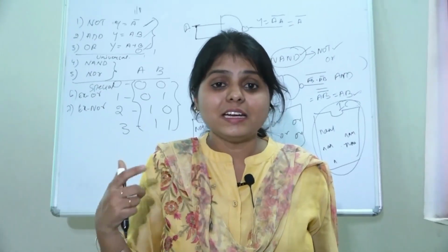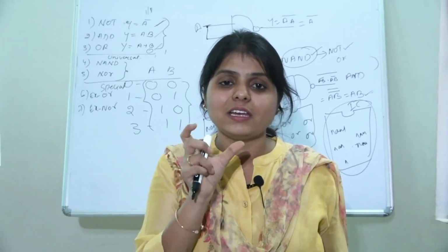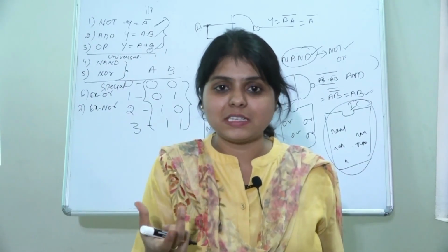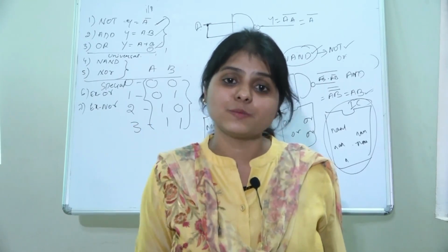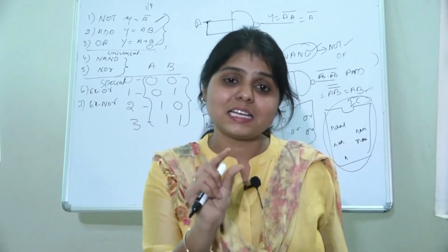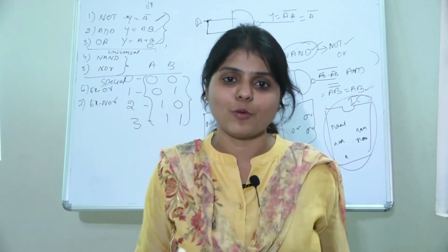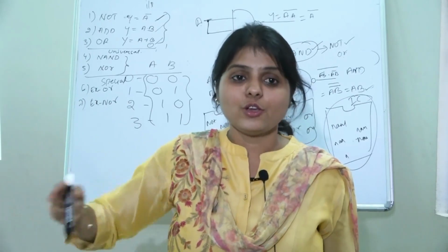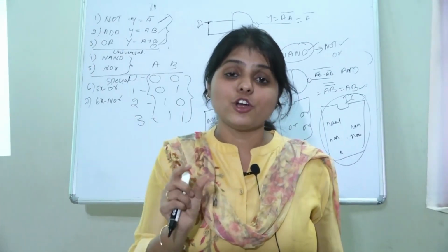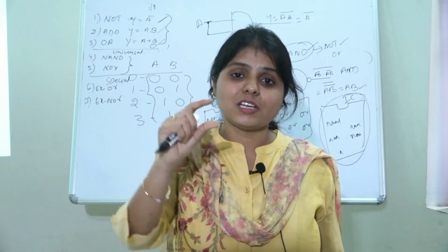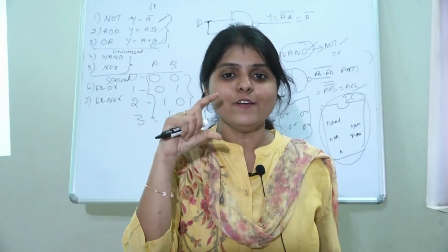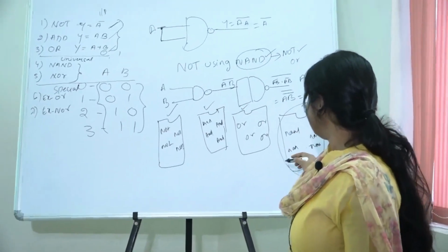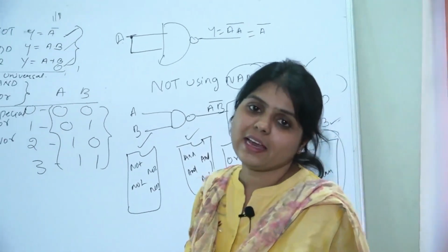So when you are designing digital circuits, all these days we are getting very narrow, slim and compact electronic devices, right? Because we are reducing the number of components being used. When you take individual gates, when you want to design a digital circuit, you have to use many different ICs. But if you are implementing all the digital logic gates using NAND and NOR, we may need only one integrated circuit. That is the reason we use universal gates, which are NAND and NOR.